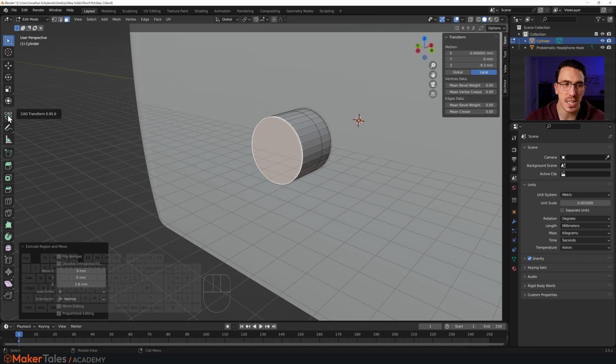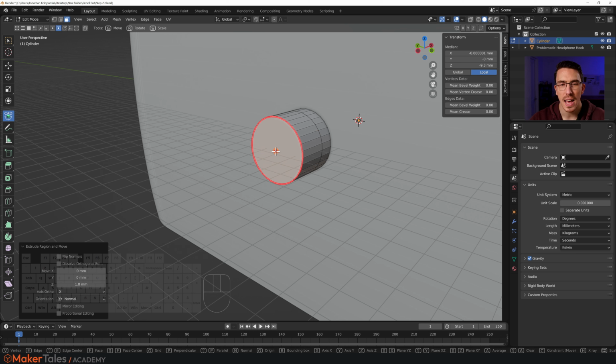We've got CAD Transforms. Remember, that's set to our quick favorites. Right click on it, set it to your quick favorites menu, so you can just press Q, CAD Transforms, and now it's on. And remember, this is now selected, so we can press S to activate our lovely tool of scaling. I'm going to press space to remove all my snapping up here, and I want face center snapping. I can click it, or I can press Shift F for face center.